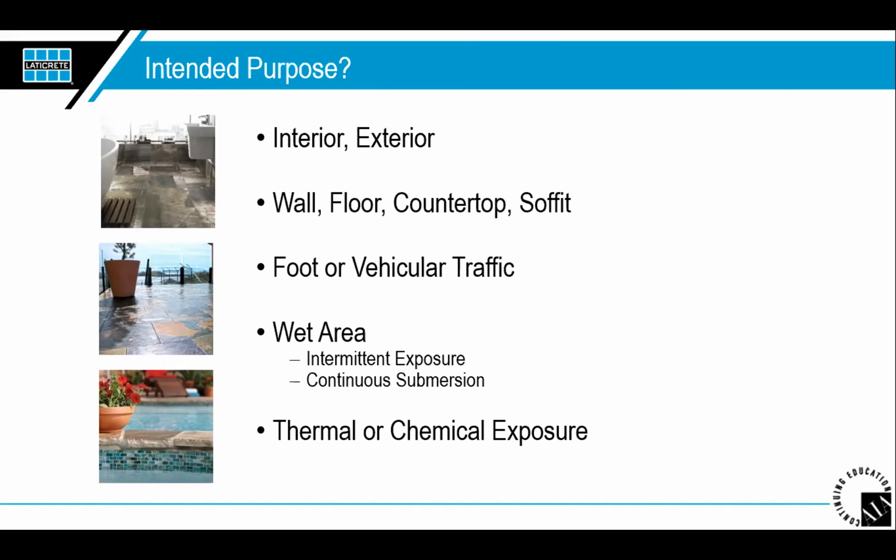If you walked up and felt the tiles versus the area that was shaded, you might notice a 10 to 15 degree difference. So in areas with a lot of windows, we need to almost treat that like an exterior application, and we need to understand even what direction the building is facing. That's going to be a big deal as well, as far as how much sunlight it's actually getting.